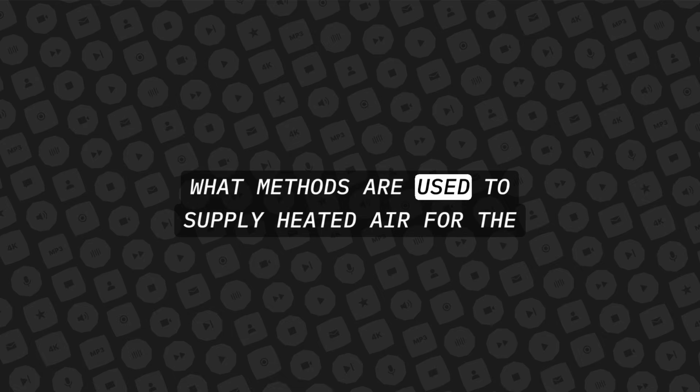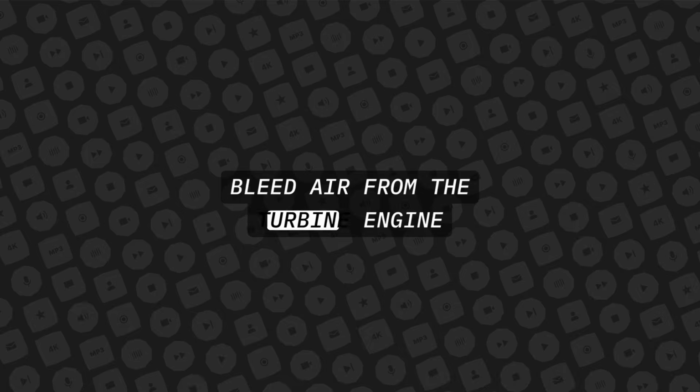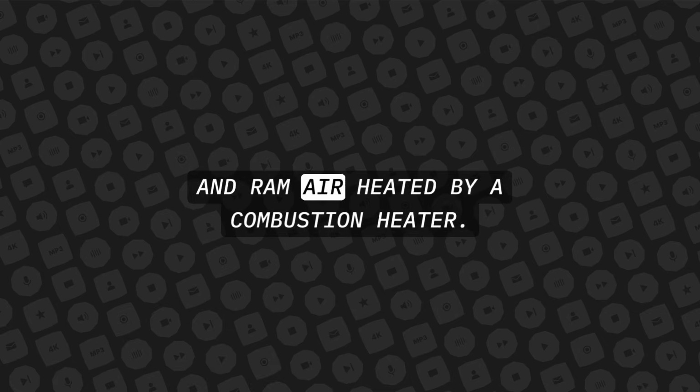What methods are used to supply heated air for the thermal anti-icing systems? Bleed air from the turbine engine compressor, engine exhaust heat exchangers, and ram air heated by a combustion heater.